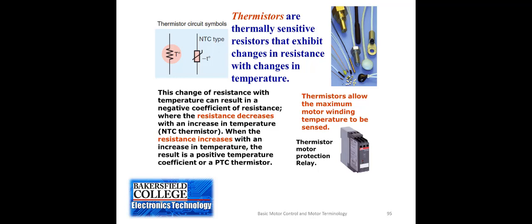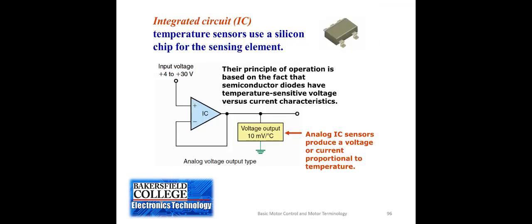Thermistors are really used because they're cheap. They're very inexpensive, and they're not very accurate, but there are times when we need to sense temperature, but we don't need super accuracy. We can buy thermistors that are built into an integrated circuit, and that contains all of the electronics that are necessary to make them function as a full sensor.